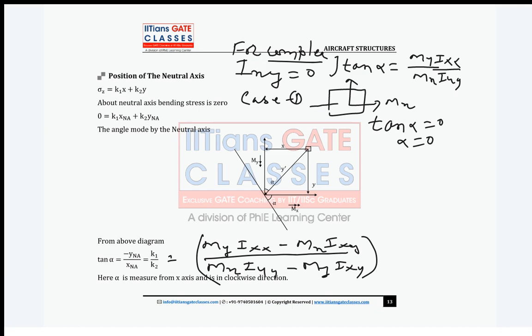That's why you guys know, right? You take, this is neutral axis. Now you all understood why x-axis is neutral axis for simple bending? Clear, guys? So any point on this neutral axis, we know, right? What is the bending stress at any point here? We all know, your bending stress is 0.